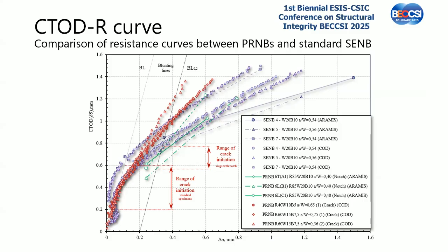And we have the red, which is the pipe ring specimens with the fatigue pre-crack here. And also we have the specimens with the notch, and this is the green line. And here is the crack initiation, which was determined like delta 5 here. And here is the last, when we stopped the test, so the values when we finished the RMS measurement of crack tip opening. So now we made these 3 lines.